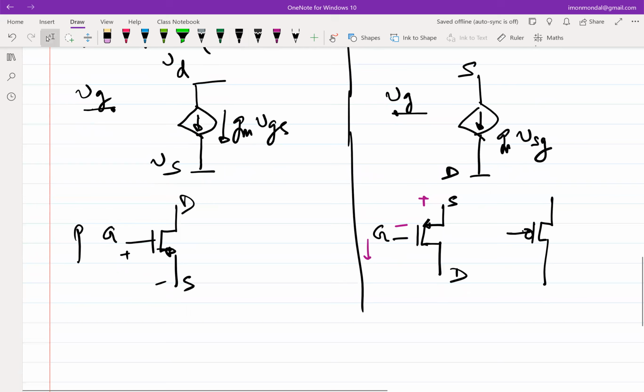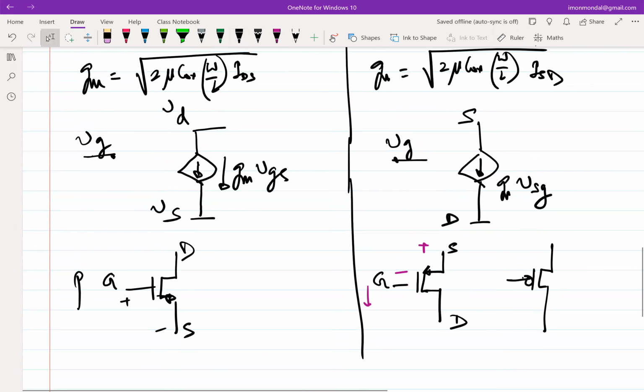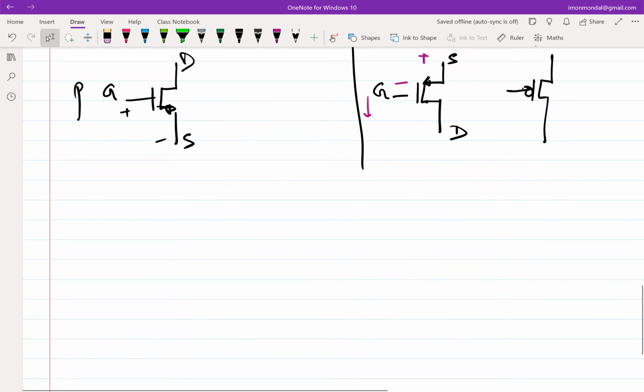Okay. In small signal, PMOS and NMOS are the same. Yeah, it's ultimately a voltage-controlled current source, right? So the controlling terminals are also the same, just the directions are different. And we have also rotated things around in such a way that it doesn't really matter. So here is another quick way, if somebody is looking at PMOS for the first time, but you are already comfortable with doing an NMOS design, right?